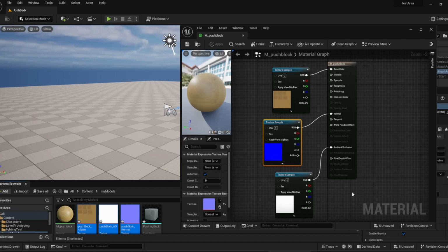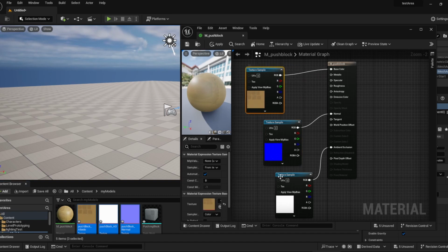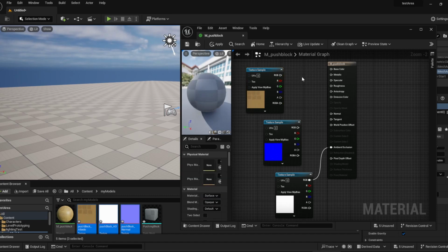And something else to note, if you are downloading from somewhere like Polyhaven, or if you're exporting from Substance and you choose to use the RGB channels, what it means is that we can have less maps in the Unreal area. If we're using the channels like RGB, say for example, if R was the base color, that would be slotted in there, and then G could be slotted into the normals. So it just depends if you're using that setup, and I know Polyhaven has that option to download your maps like that, so just in case any of you have done that, that's what's going on there. So we can save that one.